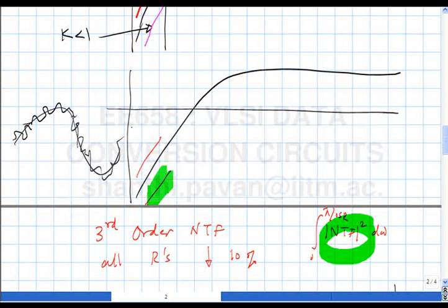And this is all available digitally. The output of the ADC inside the quantizer gives you bits which are flipping. If the RC time constant becomes too small, the flipping of the bits around the nominal value will be much more. On the other hand, if the RC time constant becomes too large, the fuzz around the nominal will become too small. So by looking at the fuzz, you can figure out if the RC time constants are too fast or too slow, and apply the correction to the modulator.